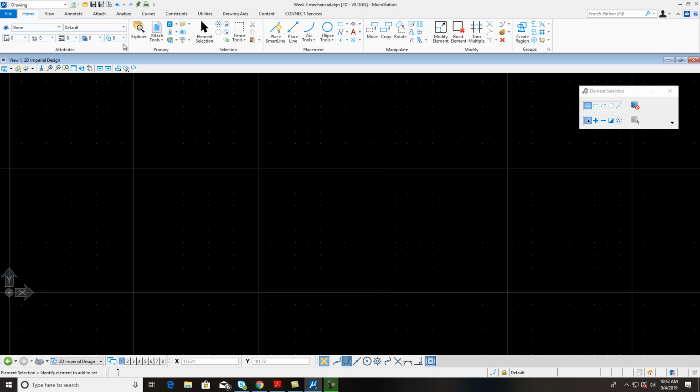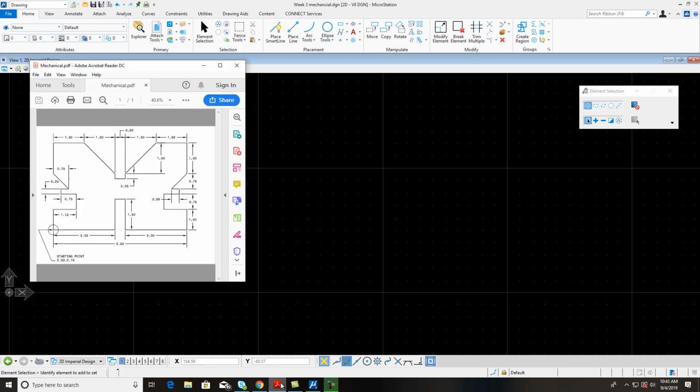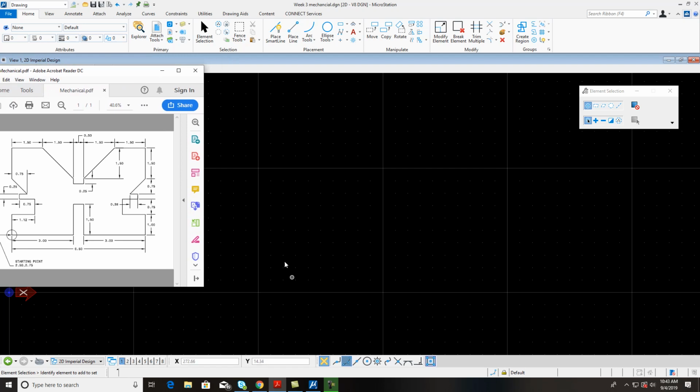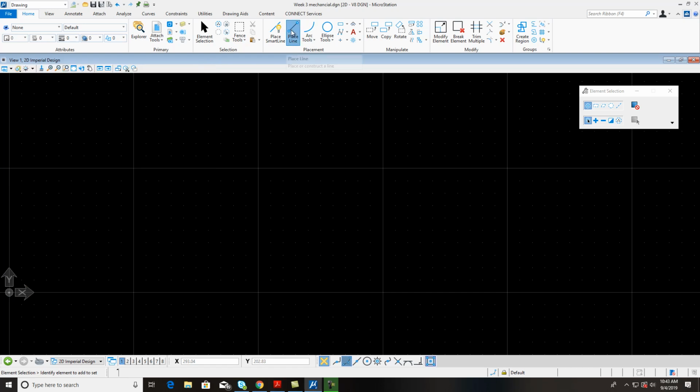And now we're going to start drawing. And I want to draw this right here. So I keep this right over here for the time being. It's really easy. It's not hard to draw. And we're just going to start out with a basic line. So hit line. And I want to type in down here at the bottom 0,0, and just click. And that made that my 0,0.